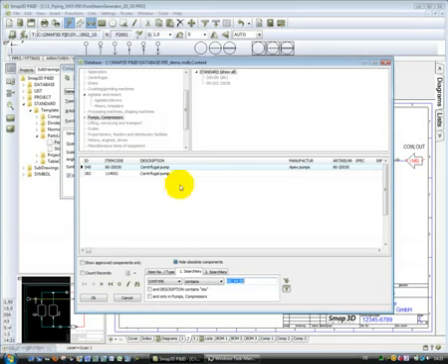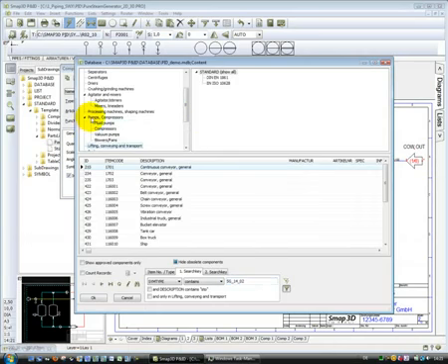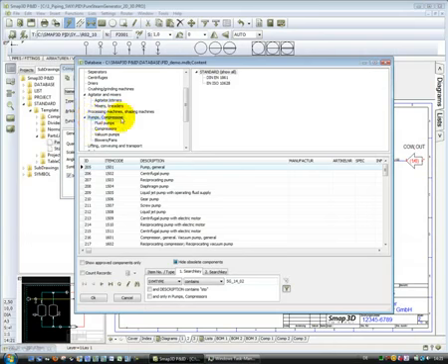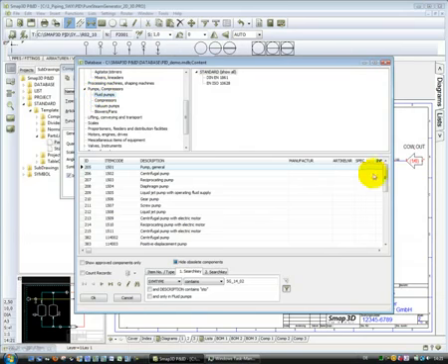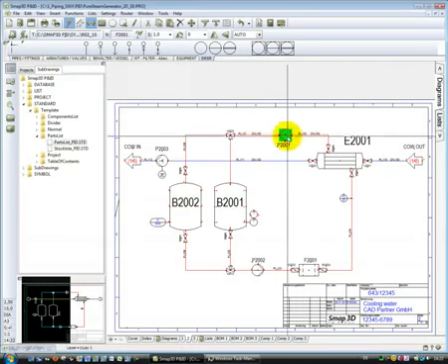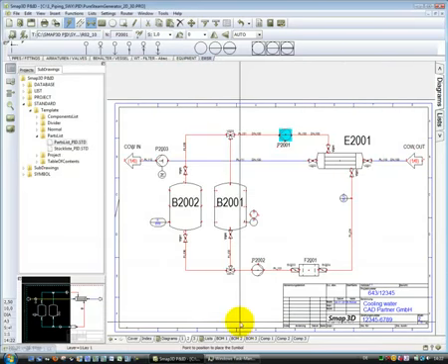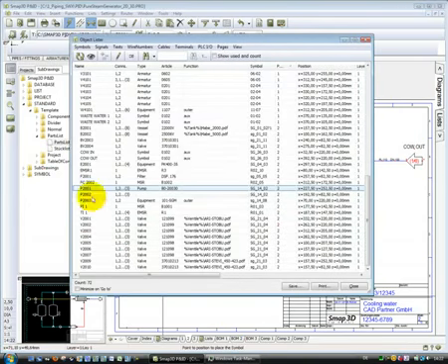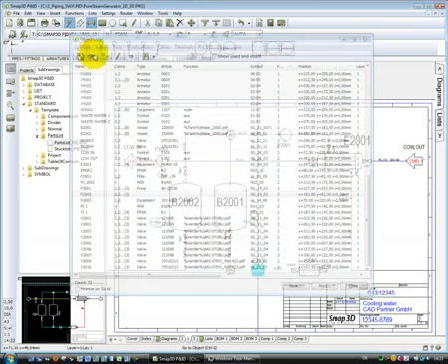With a grab to the database I go in there, and here I can now, for example, search in my structure, in my category structure, or I can create a database query. Independent how you do it, the meaning is you come to the dataset where you like to use, for example, this centrifugal pump. With a double click I assign it here, go back to my object lister. Here the information is assigned. I do the same with the other pump.